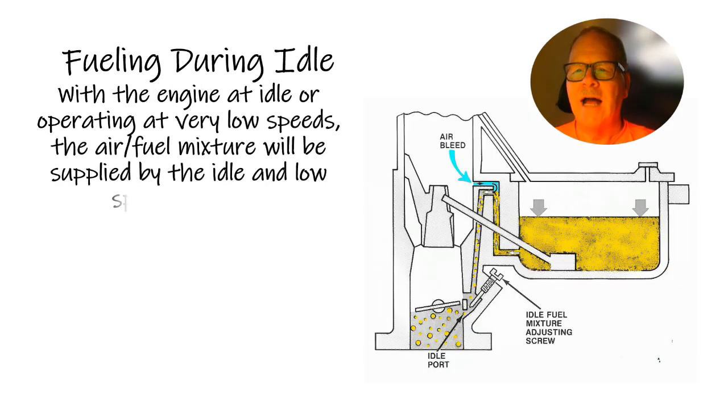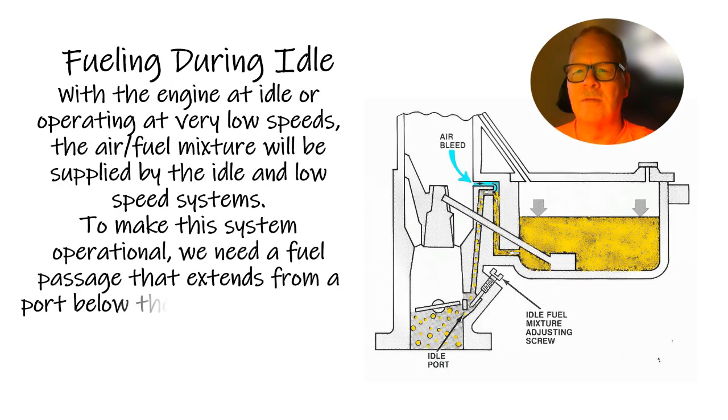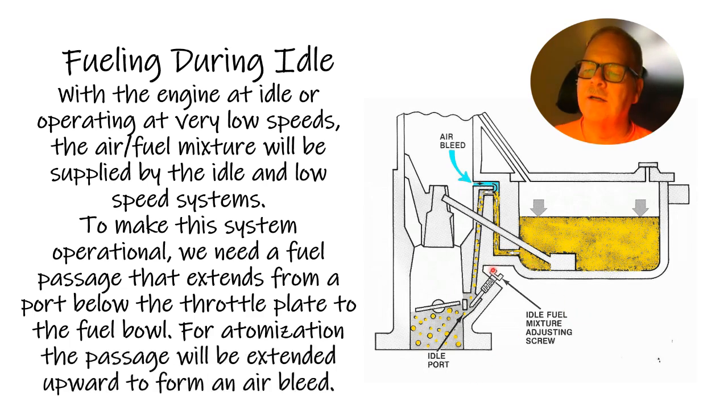Now during engine idle, the air fuel mixture has got to be supplied a different way, past this idle mixture screw. You notice how it's pointed on the end? You can screw it in and out, and you can basically feather that thing so it's idling really, really smooth. If you've got two Venturis, which you typically do, even on a 4-barrel carburetor, 2 of them are going to be the ones you're using unless you're really getting on it and you open the 4-barrel. But you're going to adjust both of those, right?